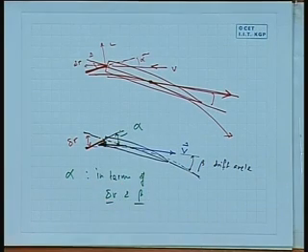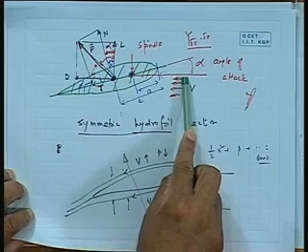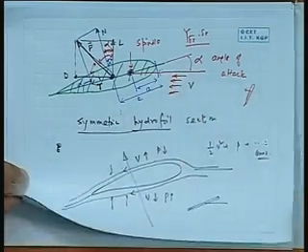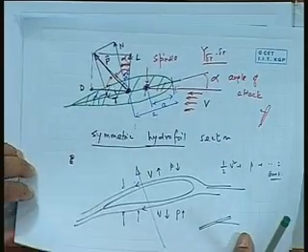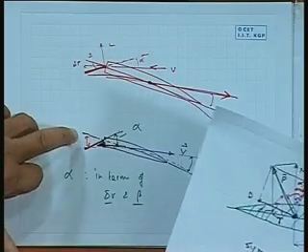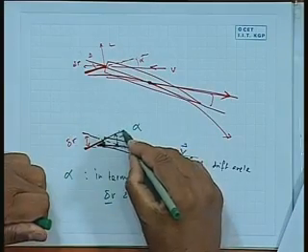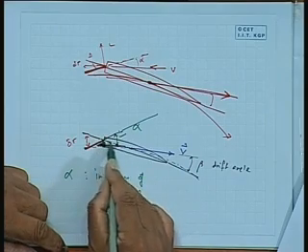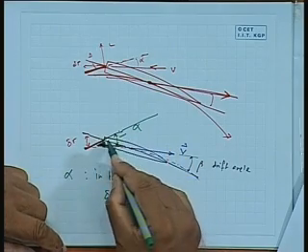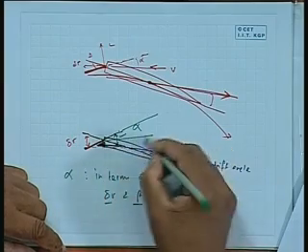So, the angle of attack, as we have found out here, this alpha is not exactly the rudder angle. I am not doing it here, but I think I can find out this to be simply beta plus this. Let me see the diagram here. This is delta r, this angle. So, delta r is actually this angle. Here the V is this way, and this angle is the beta angle.